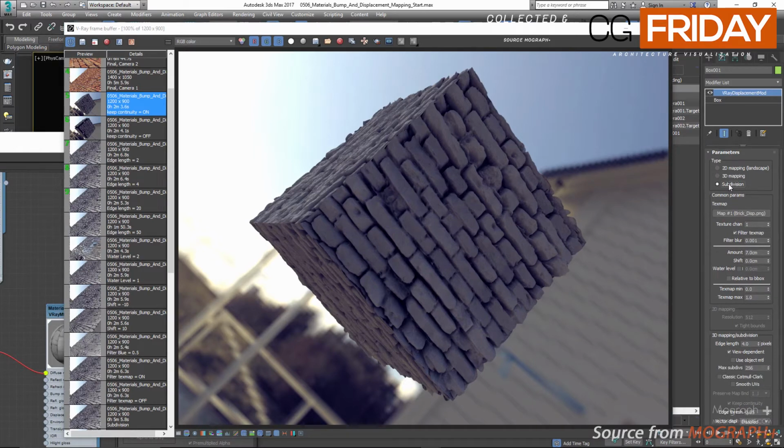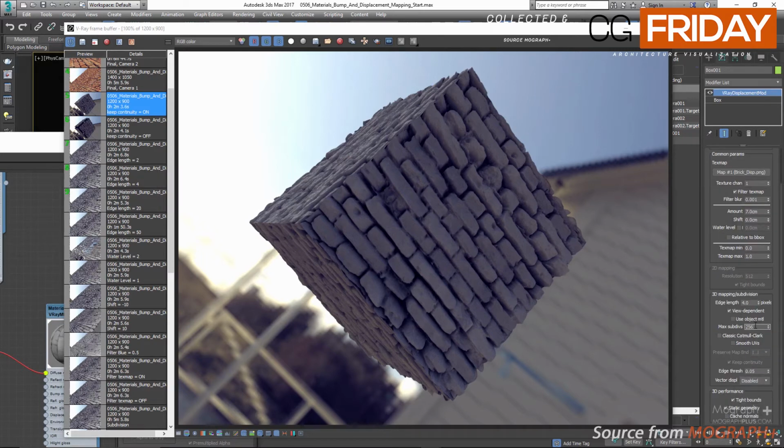First, there is max subdivs, which controls the maximum subtriangles generated from any triangle of the original mesh. So the actual number is the square of this number, as with other subdivs values. So make sure to alter this number cautiously all the time.